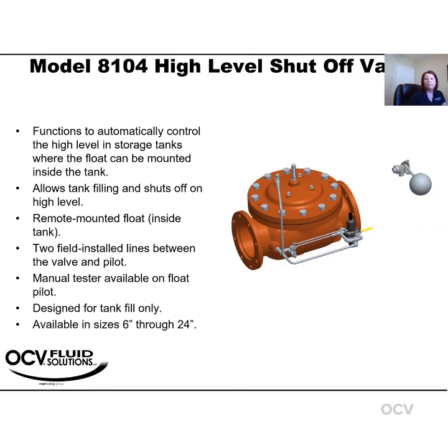Like I stated, it's remote mounted, and there will be 2 field installed lines running between the pilot and the valve itself. The float pilot does come with a manual tester, and this valve is designed for tank fill only. So we're only flowing into the tank. We're not going to flow back out. This model is typically for sizes 6 through 24 inch. We do offer smaller sizes for 4 inch and smaller, and that's typically our model 8101.